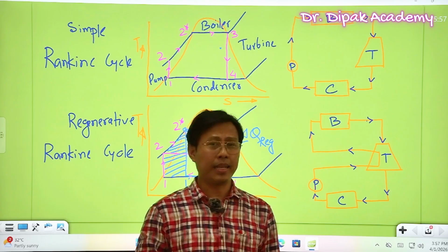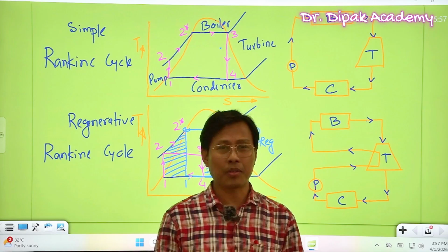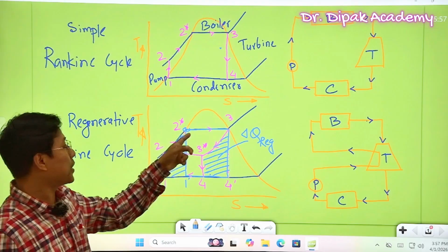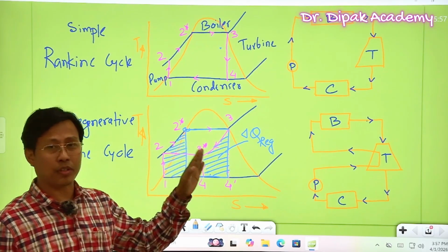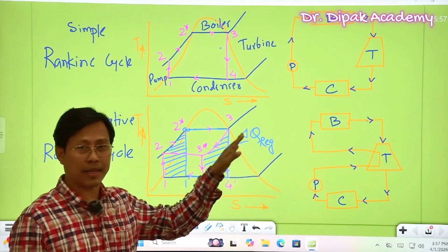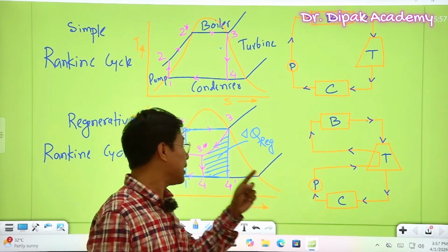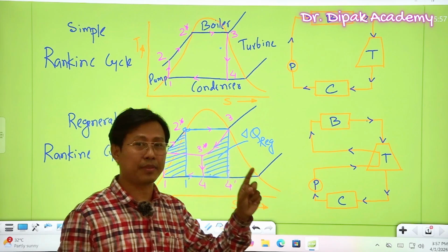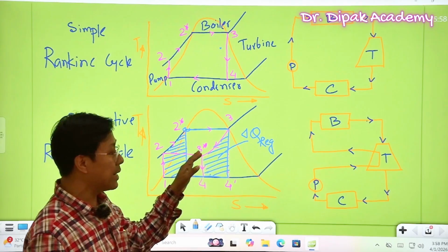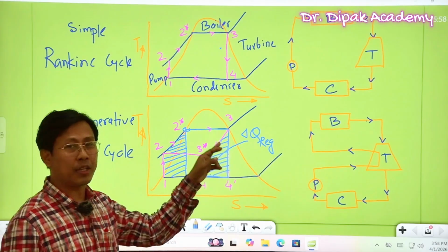Okay, so here the answer will be the regenerative cycle, because as per our discussion, when the two pressure limits are kept constant, when the boiler pressure and condensing pressure are the same for all the cycles, we can understand the regenerative Rankine cycle gives the highest efficiency, because we have studied this regenerative Rankine cycle is giving the cycle which is equivalent to the Carnot cycle.